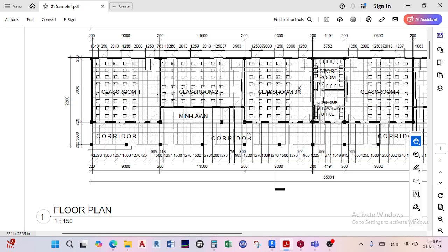And then you have chairs, right? All these things will be stationary. And then when classes are active, you have a lot of live load from the students, and most of it will actually be dynamic loading because the students will be moving, right? And when they sit for that particular moment, it will be live up until they exit or when class is over. And then you go back to a situation where you have the dead load, the self-imposed load of the concrete and the chairs and so on and so forth.